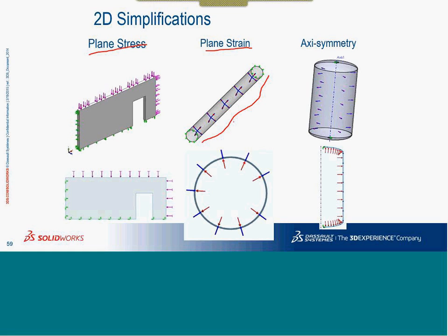On the other hand, if we don't expect too many things to be happening across the thickness, like elements which are bending as well, and they are comparatively uniform in thickness, and the stresses are expected to be in the planar direction only, then we also have these elements called plane stress elements.